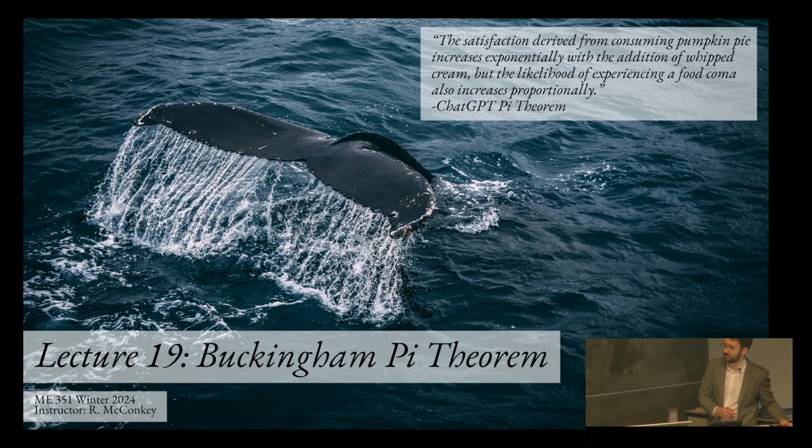It's an important theorem in that it allows us to determine non-dimensional parameters. So far in dimensional analysis and similarity, we mostly looked at things like Reynolds number, lift coefficient, Mach number. But now we're going to learn a systematic method to take a problem and distill it into its core non-dimensional variables.